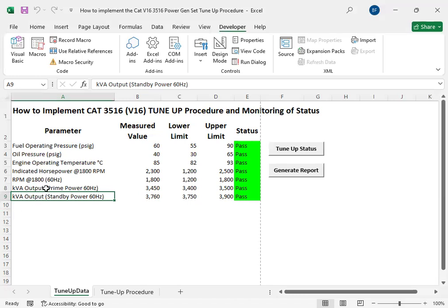And for the major causes, like it is overheated and you damage the bearings, you damage the crankshaft, then the engine would need overhauling. As much as possible, the company would avoid overhauling a 16-cylinder Caterpillar engine because it's very expensive to overhaul.